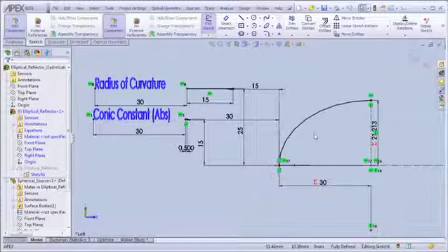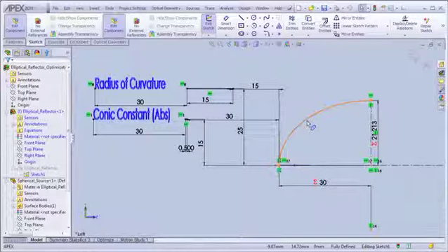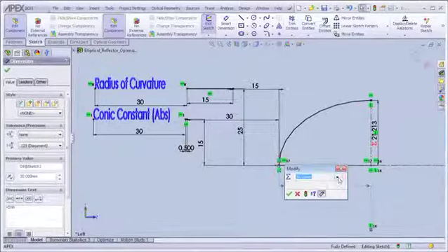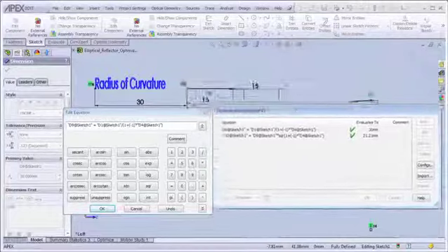In this particular example, we're going to be optimizing an elliptical reflector and a source placed close to its focus by changing the position of the source with respect to the reflector, the radius of curvature, and the conic constant of the actual elliptical surface. The interesting thing about this particular example, however, is that the variables we are defining to control the behavior of the actual curve are defined as simple line segments outside of the curve itself. However, they very conveniently reference equations which describe the actual geometry of the elliptical surface in this particular case.